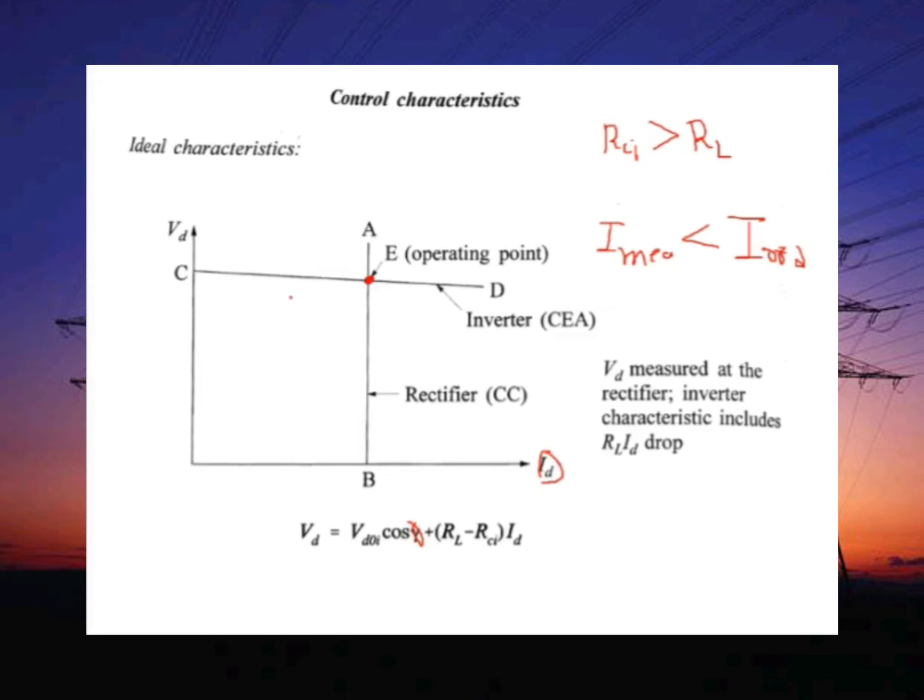So the rectifier tap changer has to bring alpha into the desired range between 10 to 20 degrees, for ensuring a high power factor and adequate room for control.